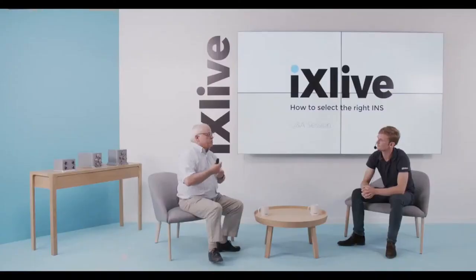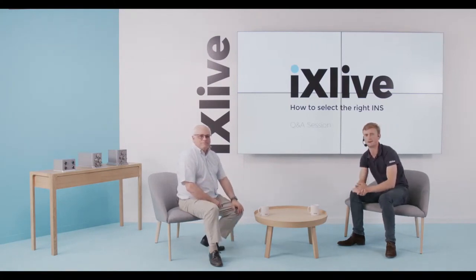Okay. And you do it first. You start by roll and pitch, and then we use heading. We do that first, and then we use the gyros for computing, and we have specific algorithms which will update the drift of the roll and pitch using accelerometer and velocity measurements. Okay. But it will be too long to go into details. This is lots of equations.